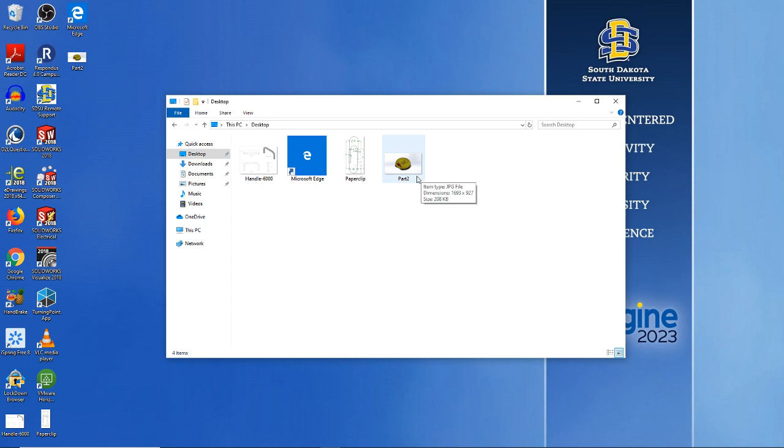Okay. For our next exercise, let's try to create a representation of this aluminum can that is housing Delicious Bang energy drink. Let's say that I wanted to create a model of this can. I could create it with linear extrusions, a sequence of linear extrusions. I could create an extrusion from the bottom, go up maybe a couple of millimeters, create an extrusion that went out, and then try to trim that off, create a circular extrusion that went up and then back. But it's way easier to recognize that this can exhibits rotational symmetry.